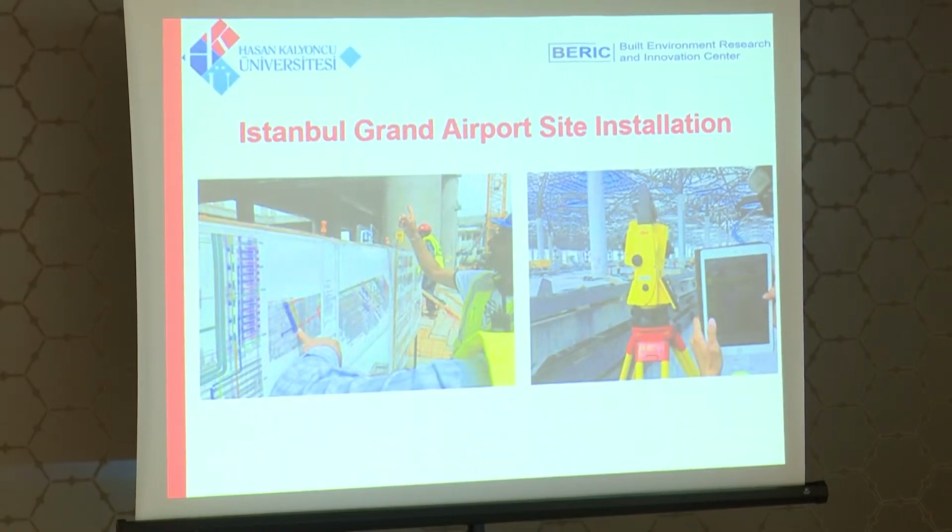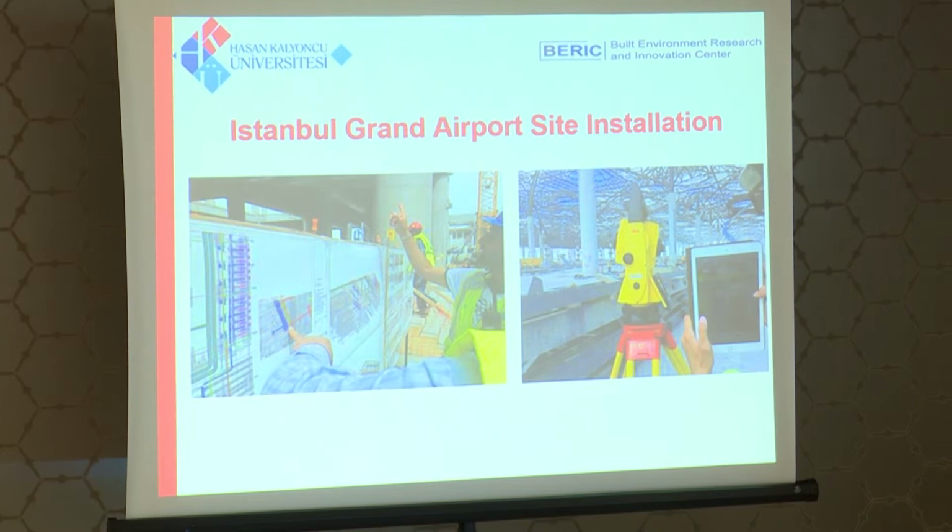And they also use BIM for quality control, mobile BIM, for example. The model I showed you is about a 30 gigabyte model. It's a very huge model, so you have to use high-spec computers to manipulate it. They had the model on tablets and checked the details of construction, to what extent the actual construction was done in accordance with the model.